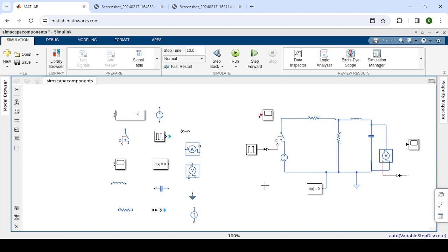Did that work? Yes, it works perfectly, because this is outputting a Simulink signal and this receives a Simulink signal, so just connect. It's important to connect it before you pass it through the Simulink to physical signal connector, because on the other side it is now a physical signal, so you have to put another one of these, which is a PS to Simulink signal converter, to convert this to a Simulink signal, then you can look at it.